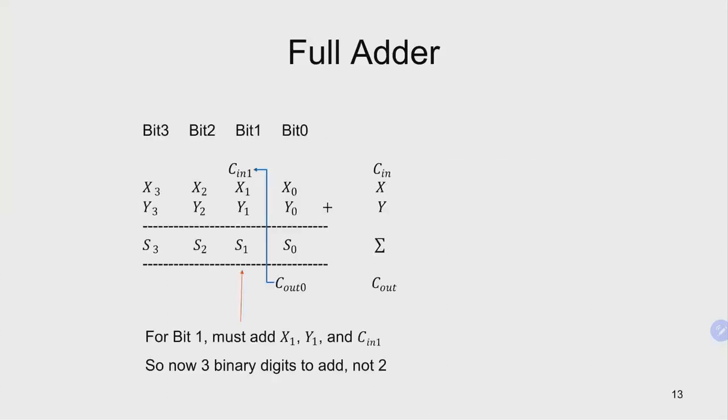So if we go back to our example, when we did our half adder and added X0 with Y0, we end up with 2 bits. One is the sum bit, one is the carry. We know that in normal mathematical calculations, this carry is included in the next column's addition. So our Cout 0 here will become an input to the next bit's calculations. So I put it as Cin 1, because now we're doing our bit 1 calculations.